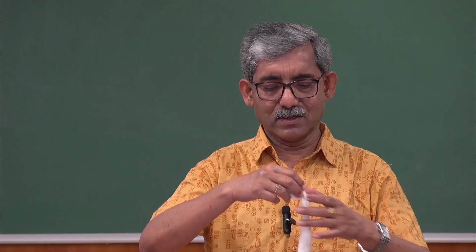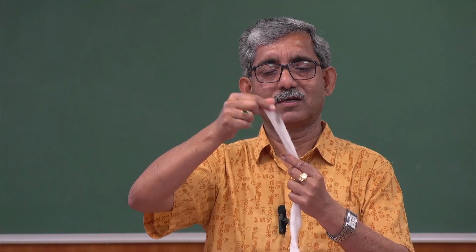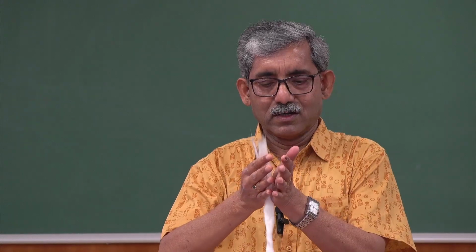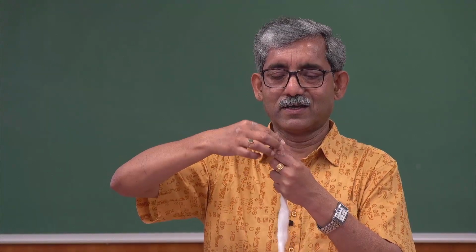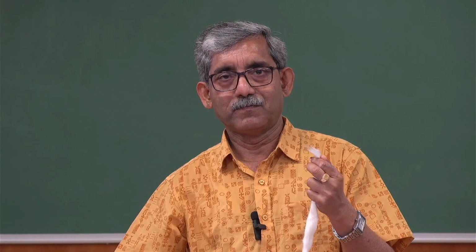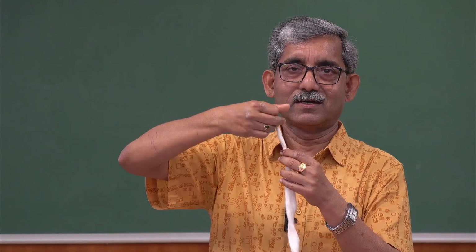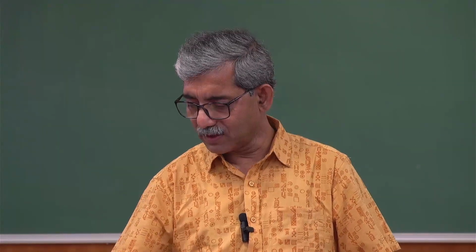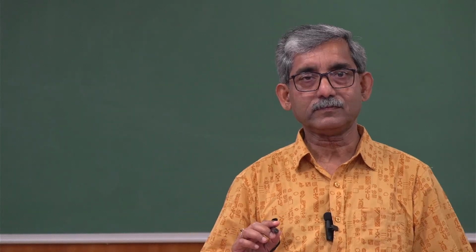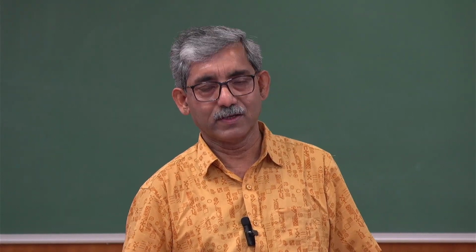Suppose this is a sliver where these fibers can simply come out because there is no lateral force, and when we apply twist, there will be friction generated within the strand between the fibers, and which will hold the constituent fibers together.